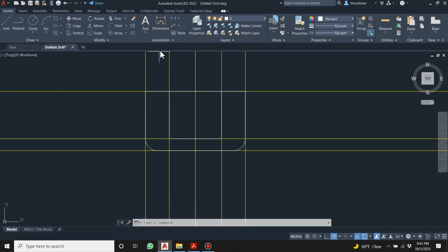Don't worry about the drawing. 0.25. Enter. M for multiple. 1, 2, 1, 2. All right. And then it looks like there's some horizontal lines going across. Now, how far do we come down? We come down 0.3, and then we come down 0.2.